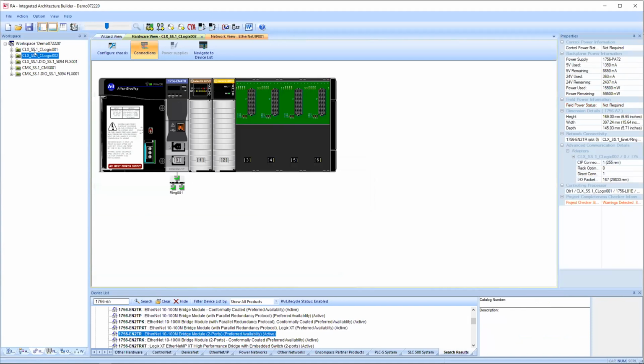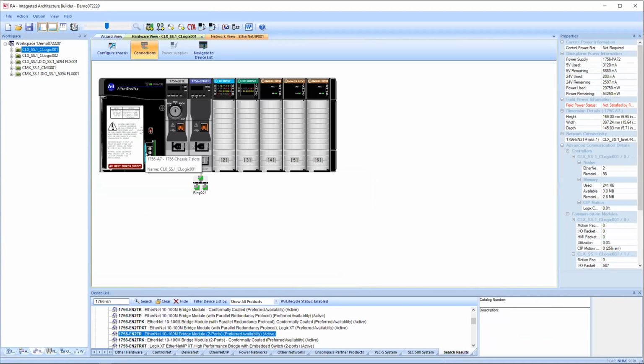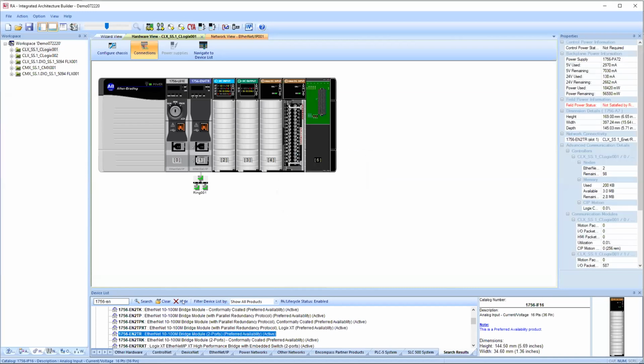So I'm going to go to my ControlLogix system, and we'll take it here. And by the way, I want to make everyone aware that Rockwell does screw things up eventually. On this, there are always going to be errors because they're constantly updating IAB. I'm going to remove one of these cards, and I'm going to pick an EN2TR, which is a 2-port comms card, and drag it in there. And you will notice it comes in as a 1756 EN4TR. Well, on paper, it is the correct thing, but they have the wrong graphic for it. This was done in the last week. So I will let you know if you come up here to About or the Help screen, you can actually send Rockwell notification that, yes, this card is screwed up, send them a screenshot, and they will generally have it fixed within a day or 2. So I just want to make you aware of this.